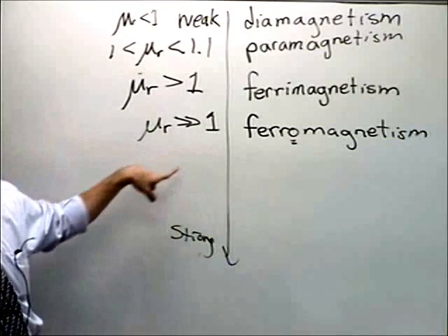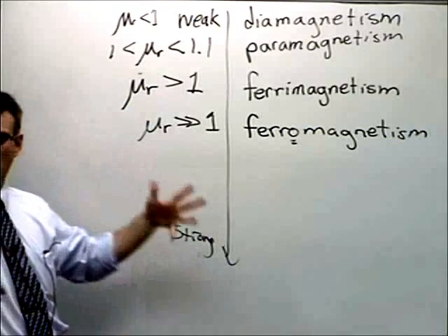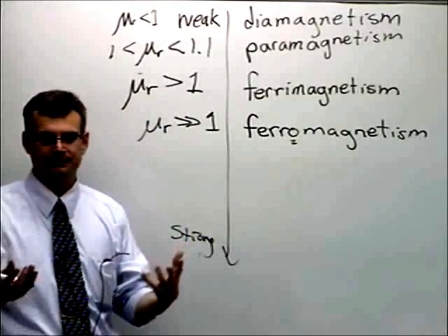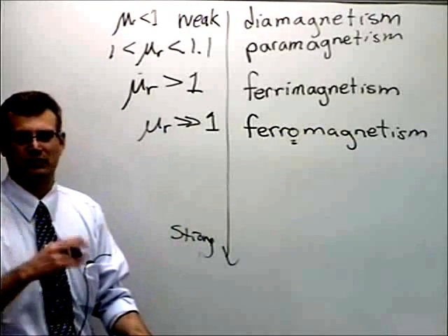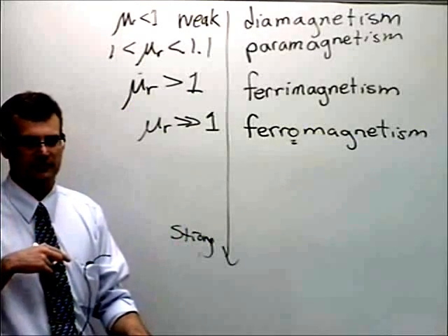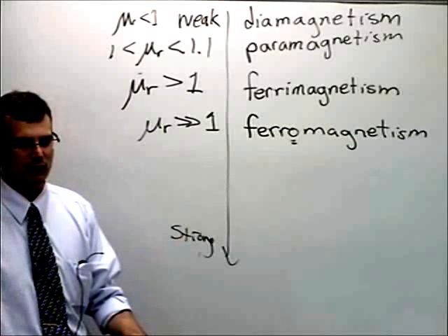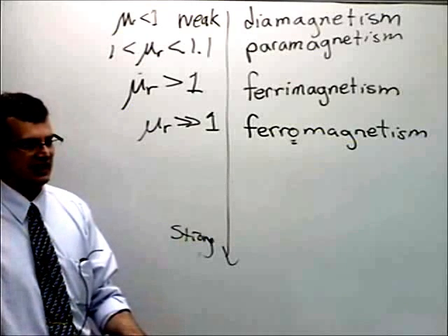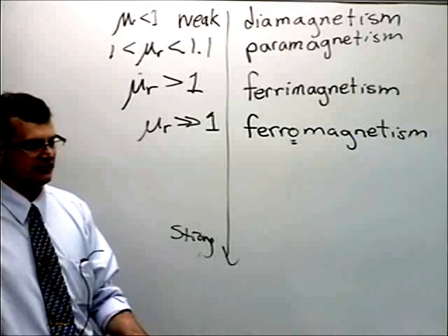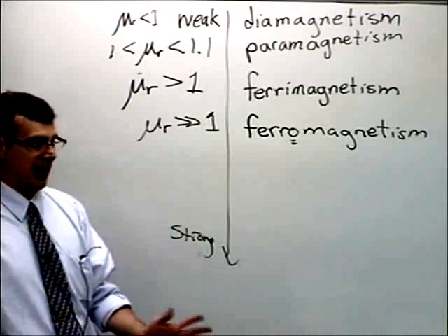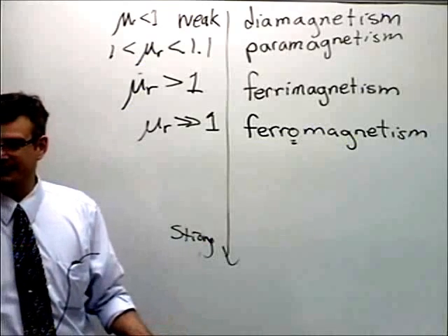And down here in ferromagnetic materials with atoms that are cooperating quite a bit, I find that the cutoff is extremely low. Most iron core transformers, for example, wouldn't work beyond excitations above a few tens of kilohertz. Luckily, power is at 60 hertz, right? So you don't have to worry about that.